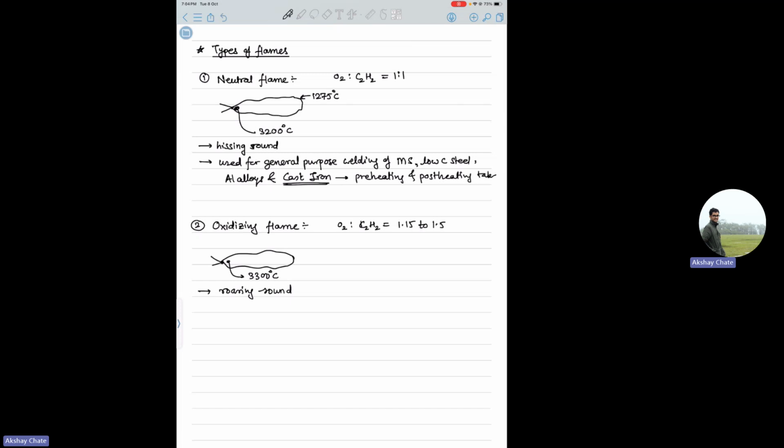As you remember, in cast iron you have flaky graphite structures, so it's prone to fracture, and you cannot directly do the welding on cast iron. You have to preheat, otherwise, if cooling rates are very high, there will be fracture. Sorry, heating rates as well as cooling rates. So for welding of cast iron, you need preheating and post heating.